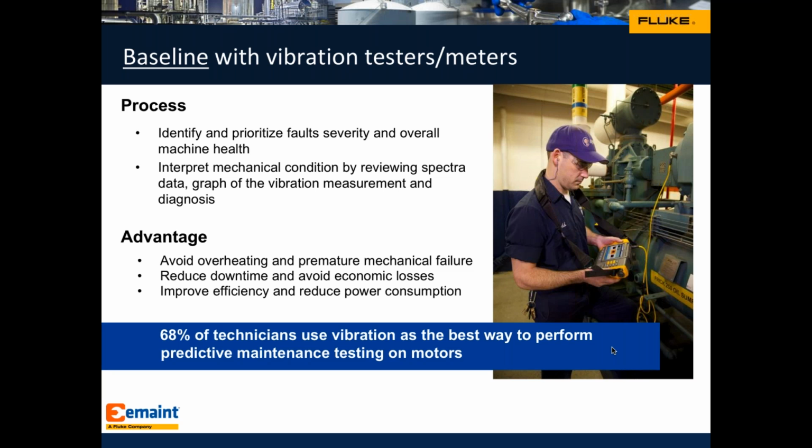So we did this, and come to find out on four of them, they're actually within range. And on the last one, they hadn't done any maintenance whatsoever in probably a few weeks, if not a few months. And they did not have at the time any vibration condition monitoring installed on each of the motors. So we ended up testing some of these, and on the last one, we did find out the bearing was actually getting warmer. We could see the temperature getting warmer, as well as from a vibration standpoint, we saw the reading going up.